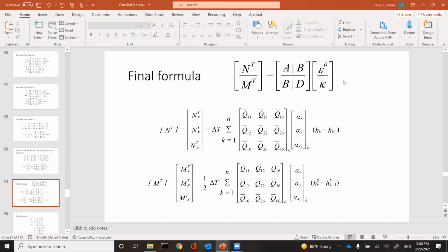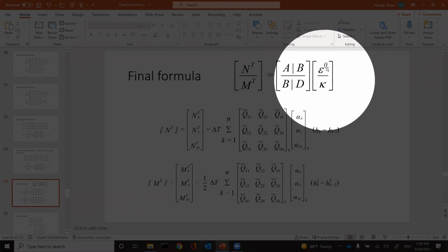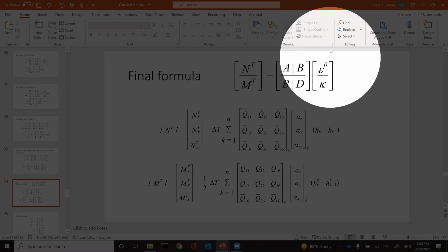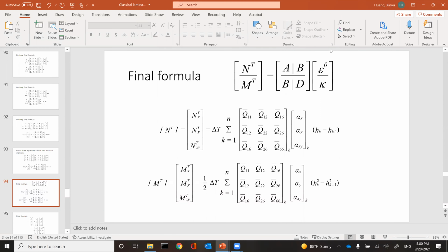Now you can experiment numerically. You put a layup together, you calculate these, and they predict how much it'll stretch in plane and how much it'll warp. This is the procedure that allows you to estimate, for a given layup, what will happen due to thermal effects.